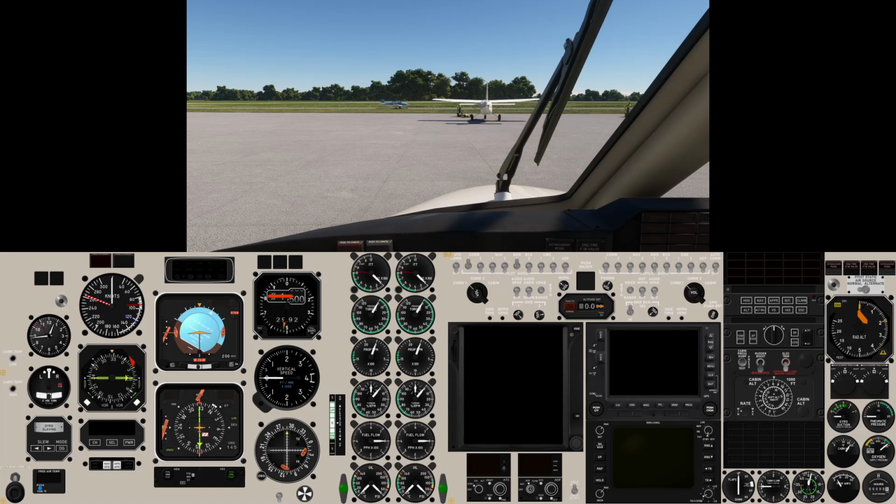So you've got a radar indicator over there, you've got your trim, your aileron and rudder trim indications, and there's lots of little analog supplementary type instruments. So you've got flap position, cabin VSI, cabin differential pressure, altitude, prop amps, there's hobbs, there's oxygen pressure, there's cabin temperature, there's gyro suction, and there's pneumatic pressure.